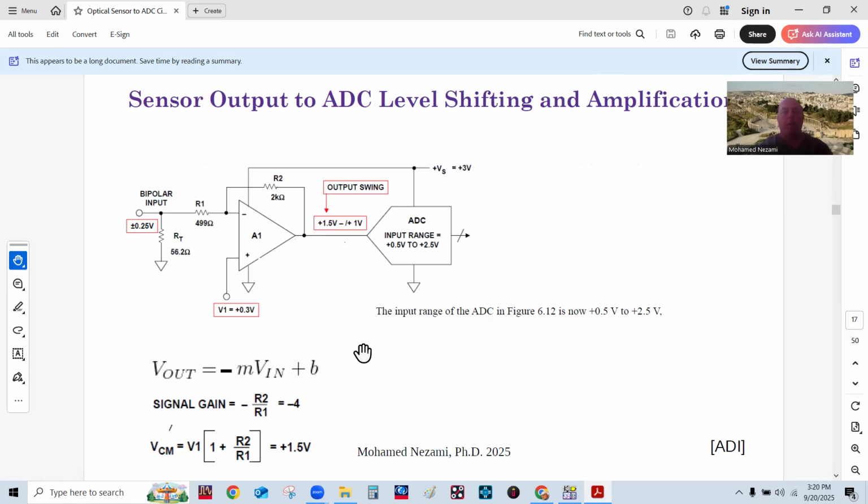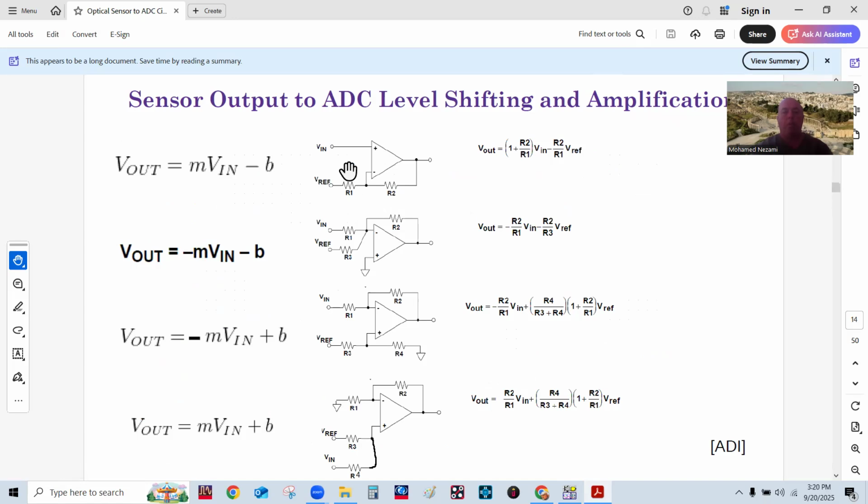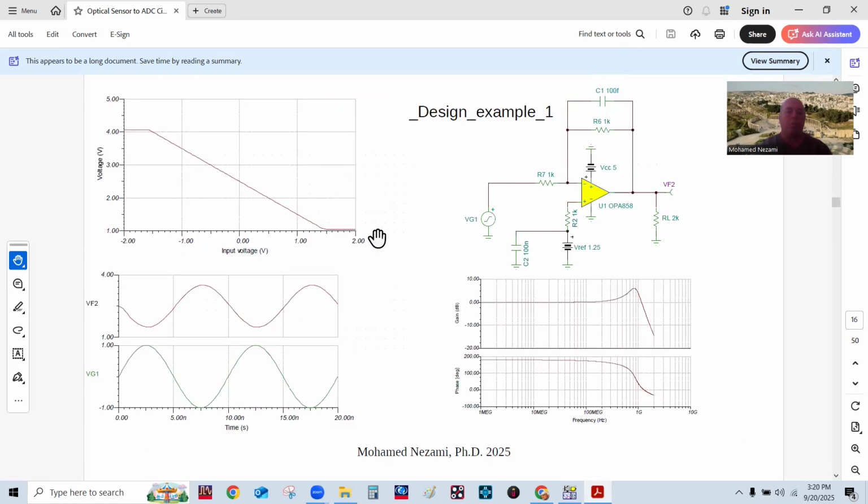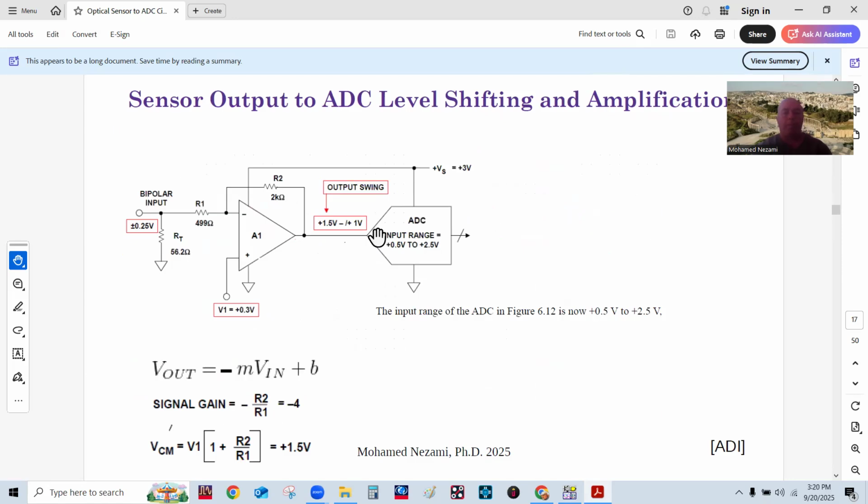Okay. And like we looked at in this case in here, of course, if the signal is in the non-inverting port, we always have this gain in here, which is 1 plus the ratio of the two resistors on the inverting port. And then the one on the inverting port, of course, is just the ratio of these two resistors, okay? So let's do the same thing in here.